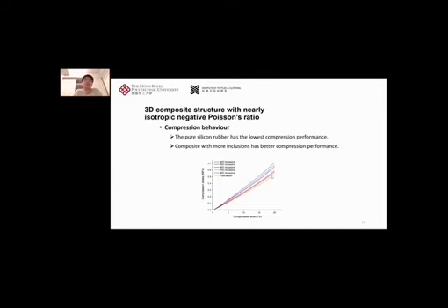They don't increase a lot, because even when we put 800 inclusions, it's still a low volume fraction of the carbon fiber, and putting in more inclusions actually puts more air inside these composites, so it doesn't help with the mechanical properties. So this is one problem of our composite.